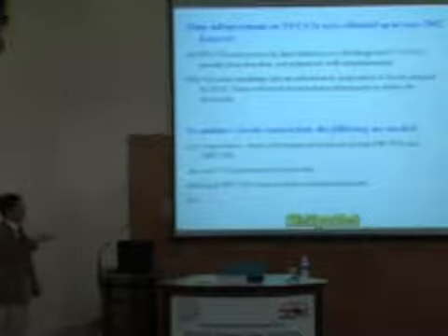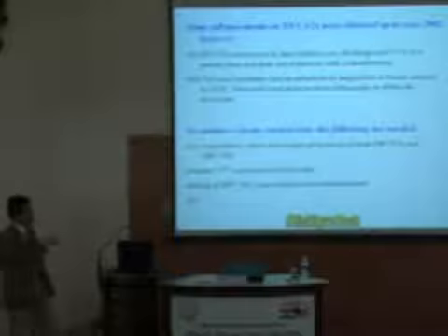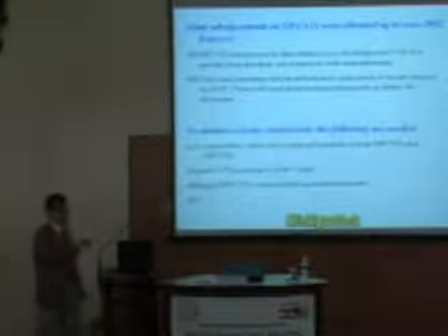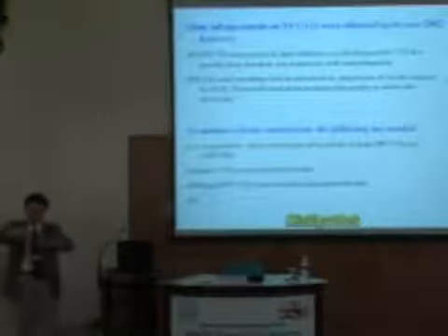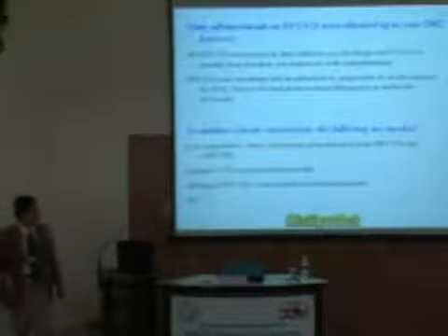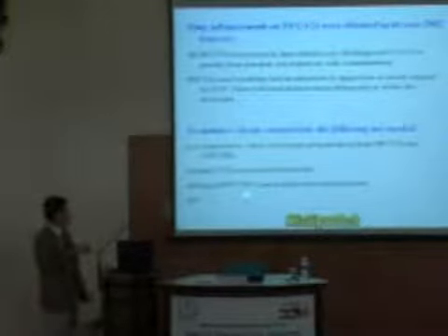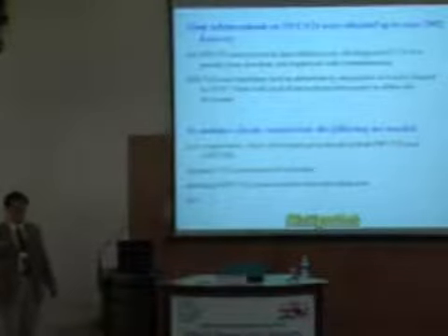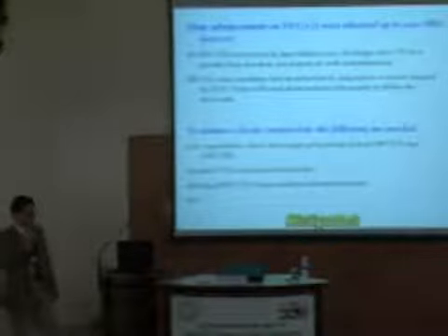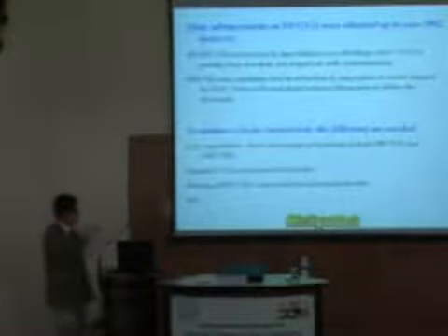And you will need to be able to deposit carbon nanotubes across a pair of desired electrodes. For instance, within the chips, you might have 1 million pieces of electrodes. You want each pair of electrodes to have only 1 nanotube aligned across them. And also, you have to be able to sort single wall carbon nanotubes into semiconducting tubes or metallic tubes, so that you can choose only the same type of tubes for your applications. And so on. The list will be very long.